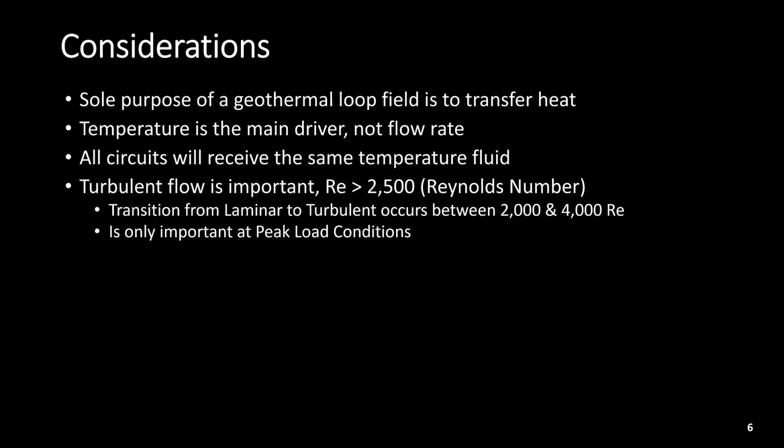So I'm not sure 2,500 is a magic number. I would encourage you to look more at numbers above that. But once you go above 4,000, you're pretty much guaranteed you got turbulent flow. And anything higher than that really doesn't buy you a whole lot.